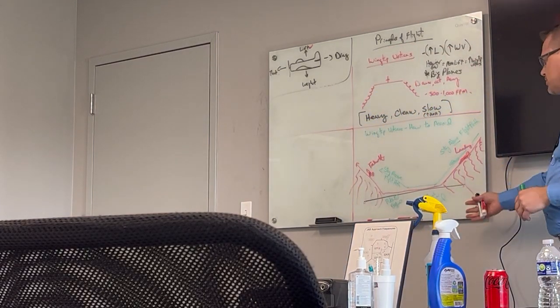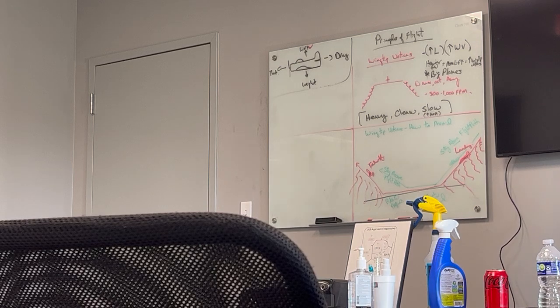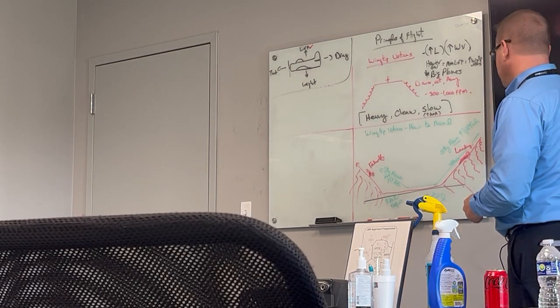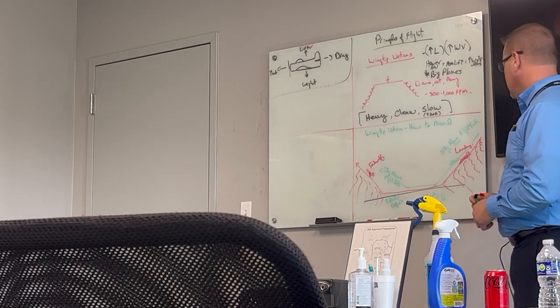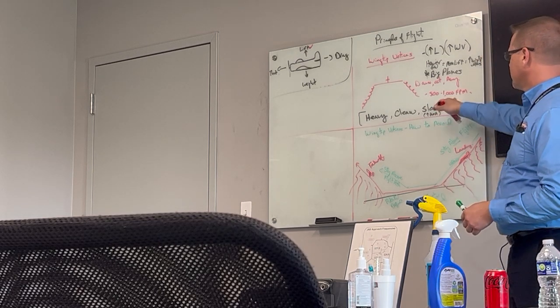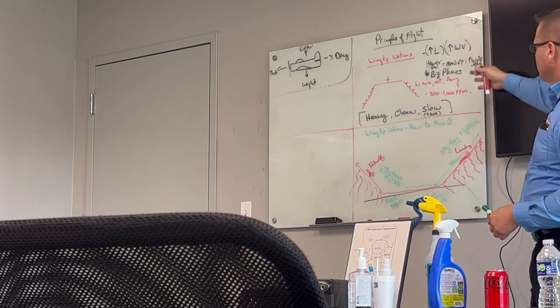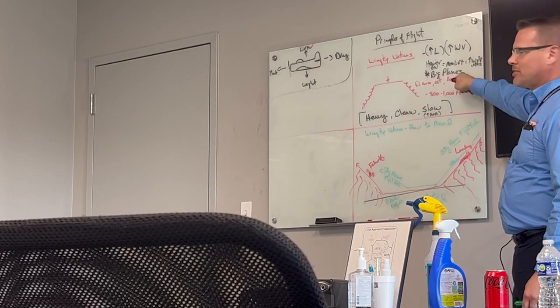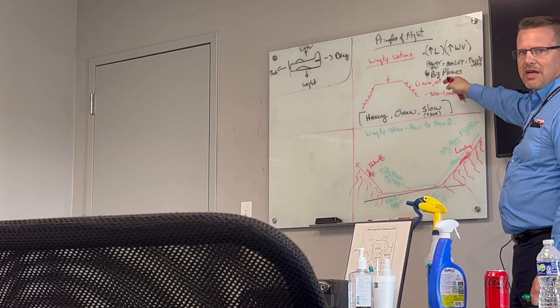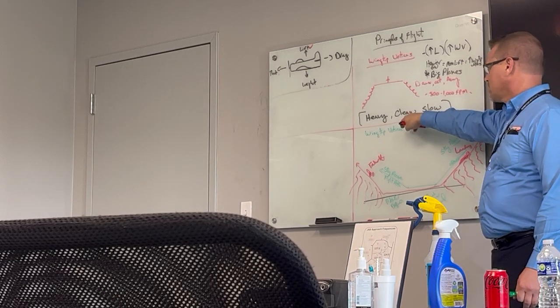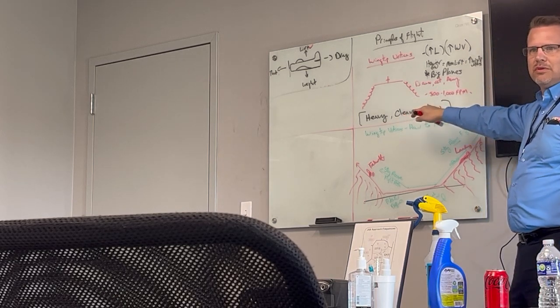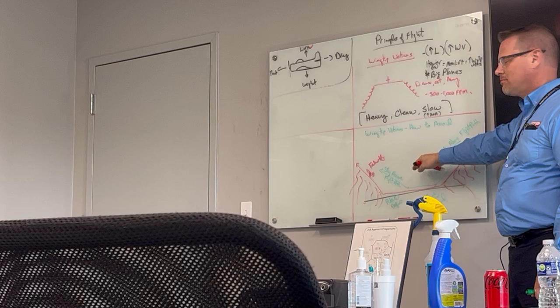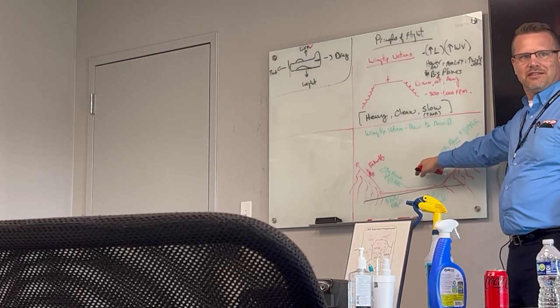So I hear a lot of people call this the bowl method. I've been hearing that a lot lately, I've never heard that before, but yeah, it looks like a bowl inside of a bowl. So basically you're premising it with what are wingtip vortices, why are they dangerous, what are we concerned about? Well, it's the bigger planes, the heavier weights. When are we concerned about it? Heavy, clean, and slow. Well, that's typically when we're taking off and landing.